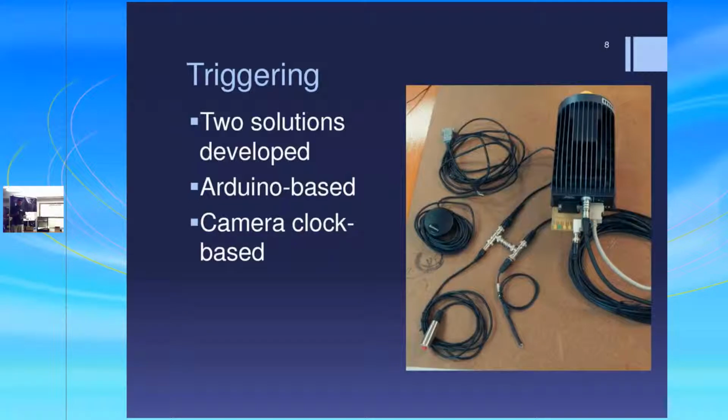The PC clock is used to get the start time and must be synchronized to within 500 milliseconds of the true time. When the program gets the time from the PC clock, it knows that the next 1 pulse per second pulse is the start of the nearest second. Getting a little feedback.